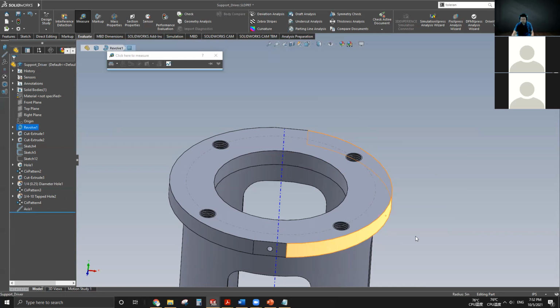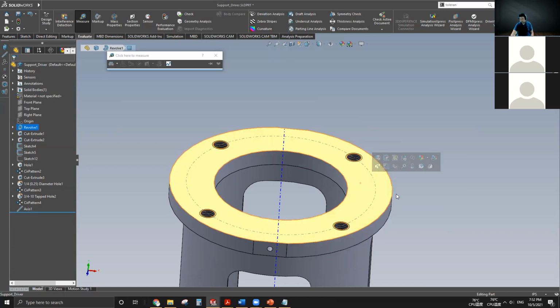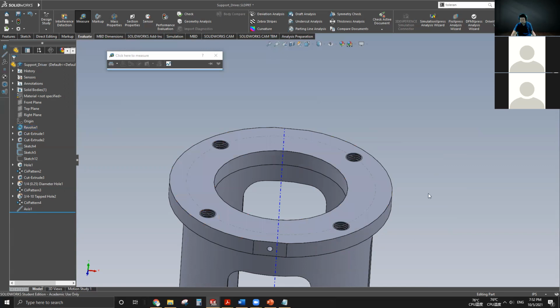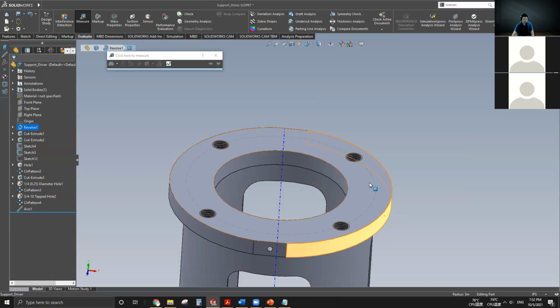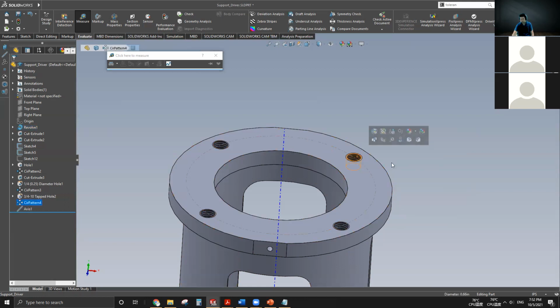And if you want to do a really good job, you can reference the top surface as well, telling them the tapping should start from the top surface. But this one is optional because pretty much every machinist would realize that from your drawing. So think about it. If you don't reference this outside diameter, what will happen? Can they still locate the tapping point of this hole and start drilling or tapping? Can they still do that?